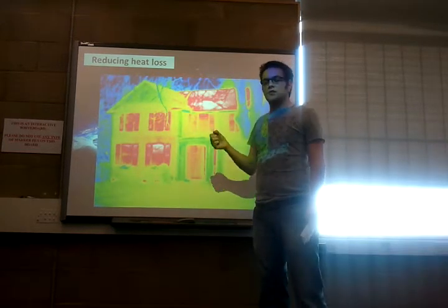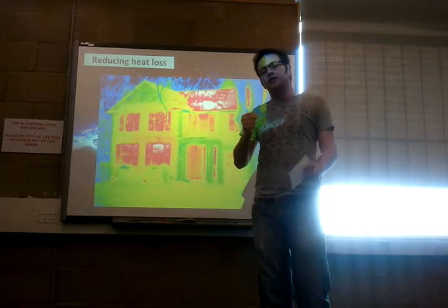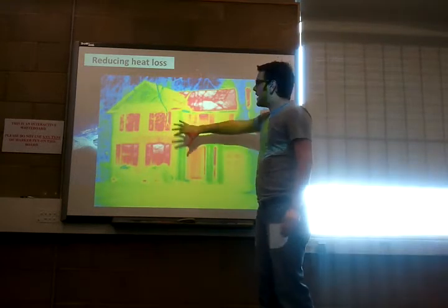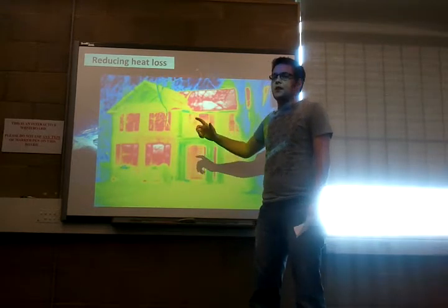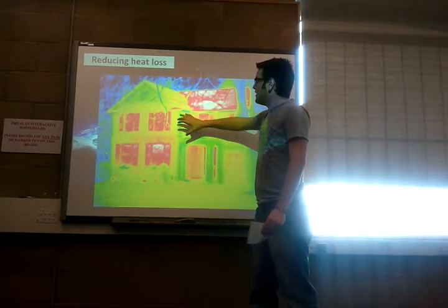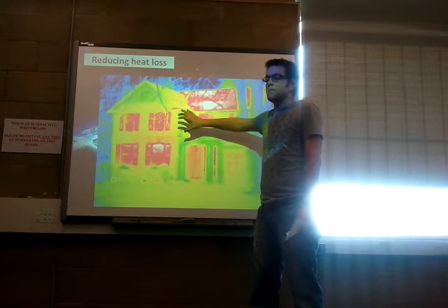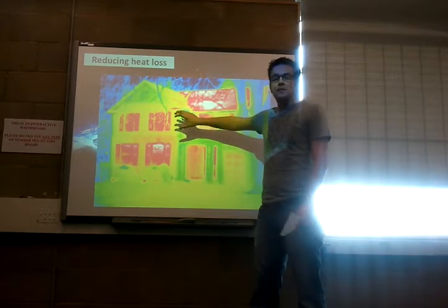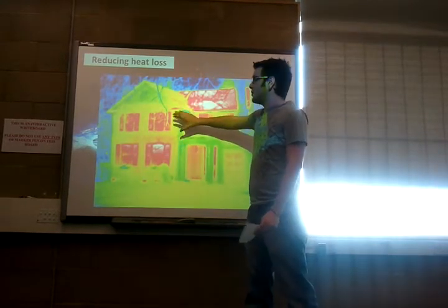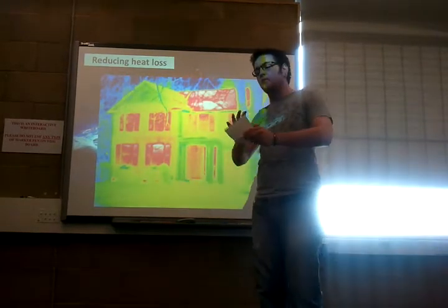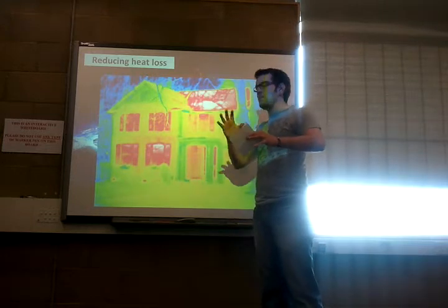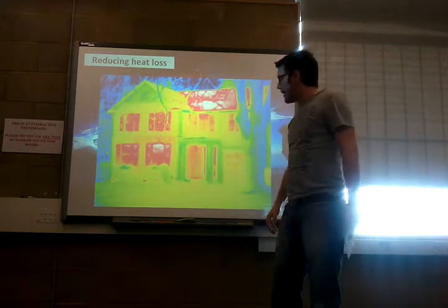So what does that mean? Conduction, as we said, is the heating of molecules in a solid material. So as the heat travels from the outside, it's not just metals, although metals are particularly good at conducting heat. In this case, even the molecules in bricks, or in the mortar between the bricks, and the molecules in air are vibrating as well, so the heat will gradually travel through them and be lost to the outside.